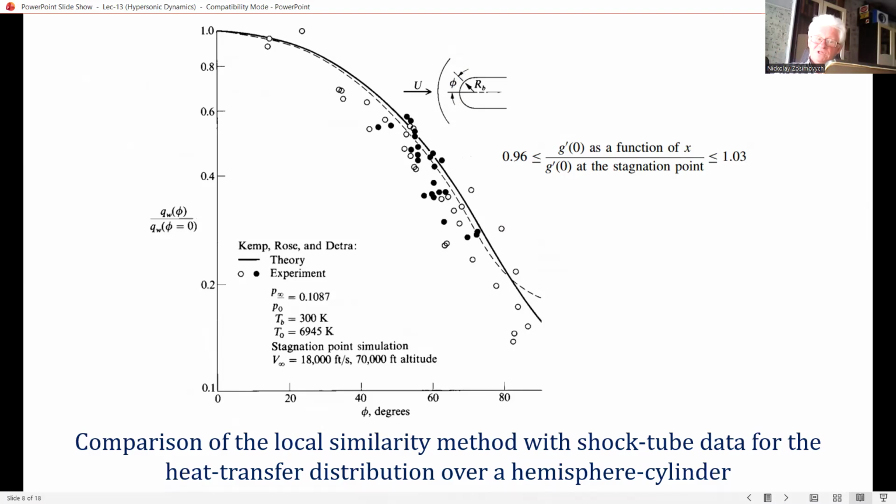And therefore, the history of the development of the boundary layer from the leading edge to the local station is not properly accounted for in the local similarity method. However, the upstream history of the inviscid flow is transmitted to the local similarity solution, as the local values of u, h, etc. are influenced by the history.